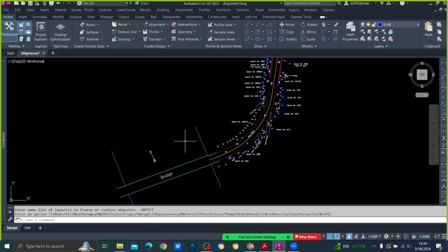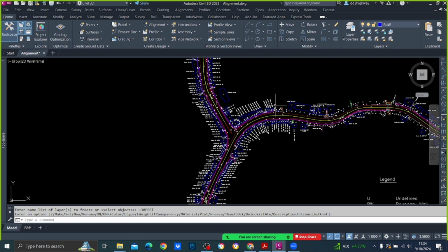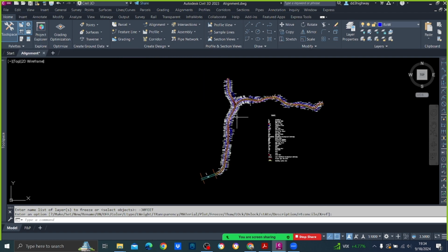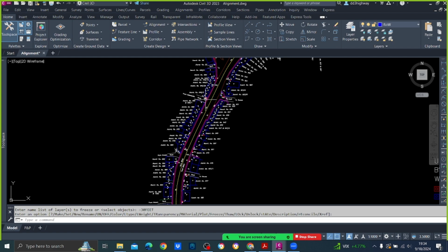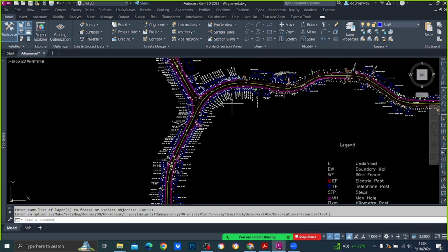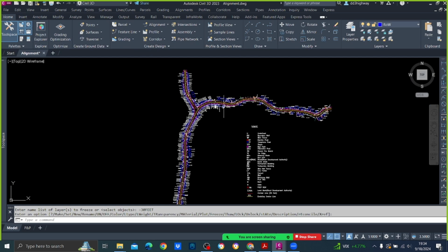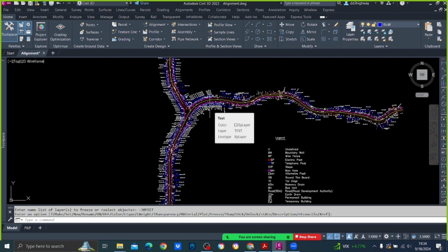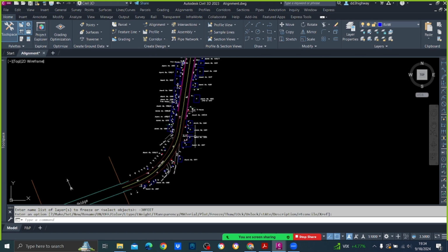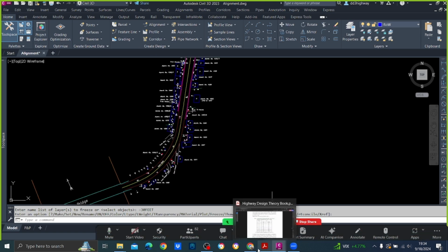So, in urban areas, you are usually going for 50 kmph, right? And rural areas you are going for 70 kmph. Now, by the look of this site, you can see this is an urban area. Can you see? So many houses or buildings are nearby. So this is an urban area. Therefore we will select 50 kmph.